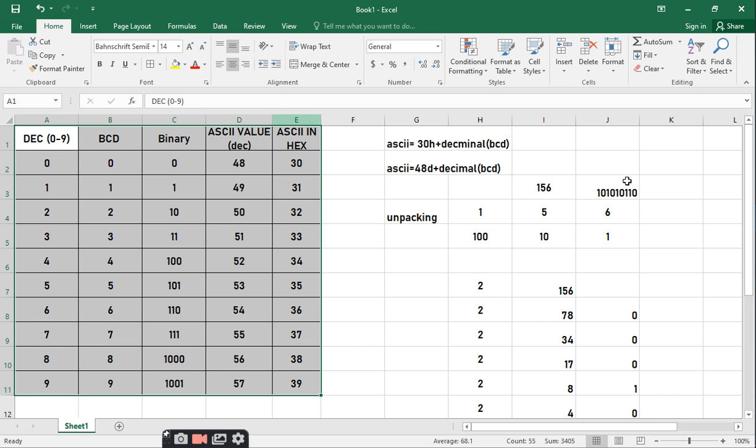Right. So now we will try to write one program for this. In order to obtain the ASCII number from the decimal number, we have a decimal number and we have to convert that into ASCII. Take that number and add simply your 30H. So it represents a simple addition program.